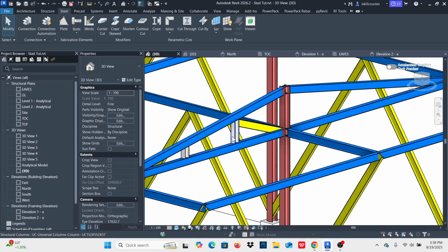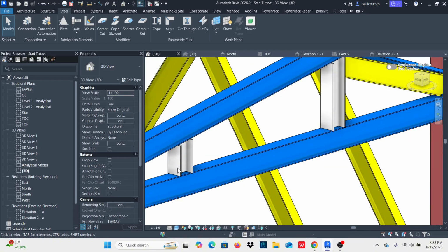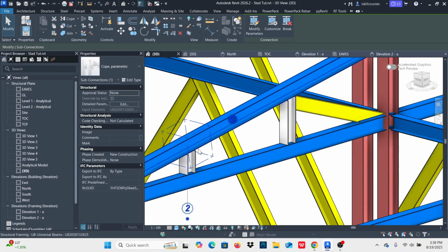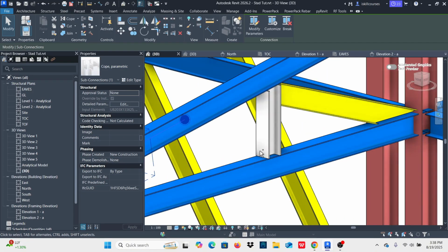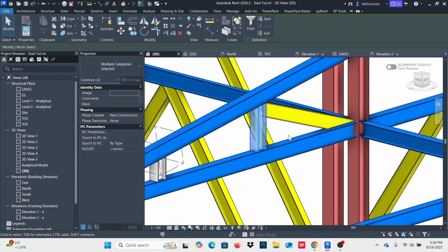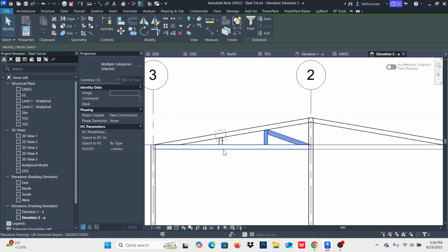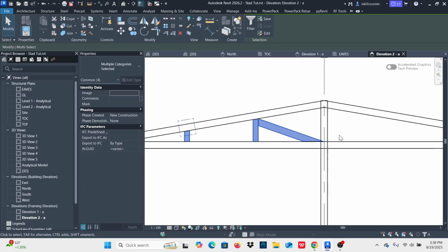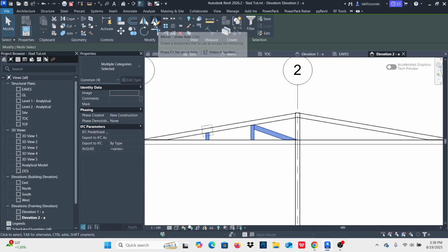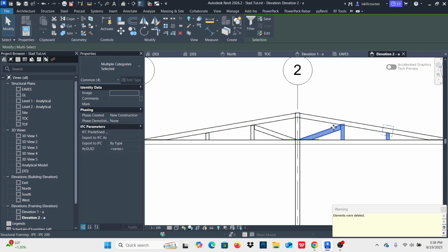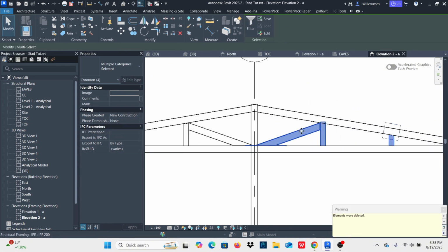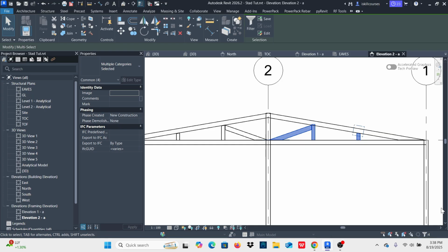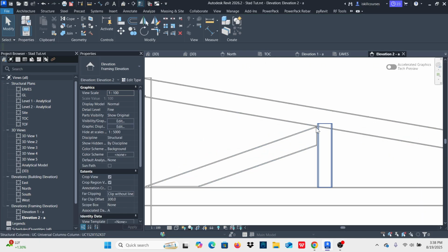Now on the other side, I think I can mirror, but I just need to fix the copying a bit because it's at an angle, so it doesn't flip on the other side properly. So I'll just select these members inside, then go to that particular view. Is this one selected? Okay, I'll select it from here. Right, so I'll mirror this one. So I'll just pick this one here and mirror against that one. If it doesn't mirror properly, I can always fix it.